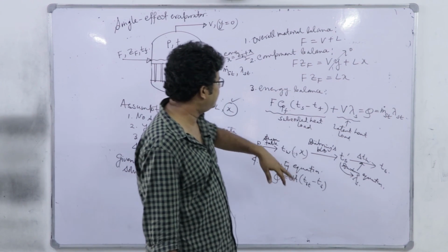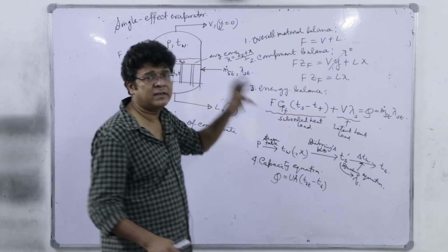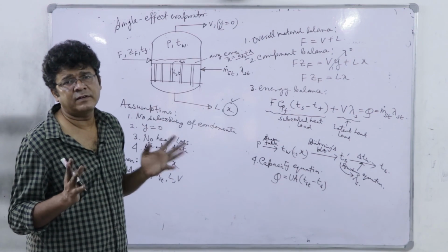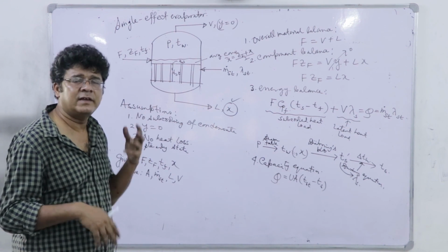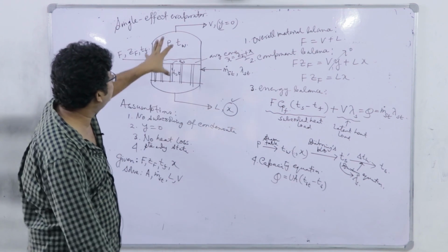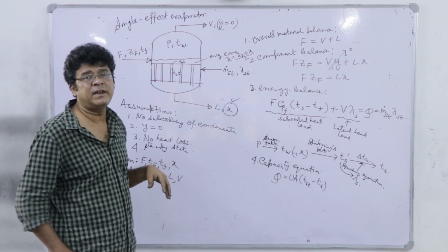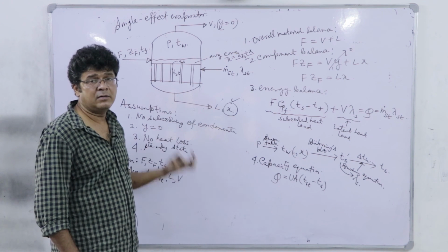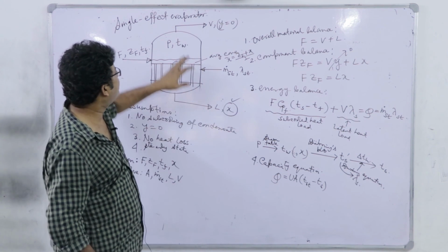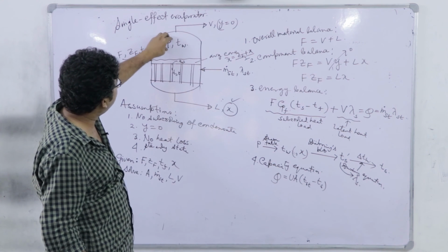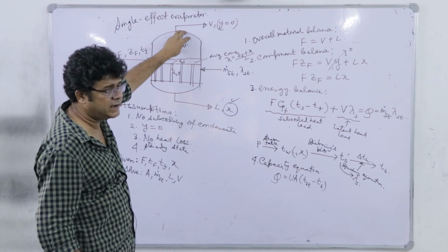We know X, and we have to fix certain pressure. Generally for single effect we can use this atmospheric pressure, but if it is heat sensitive then we may go for vacuum. That depends on the specific type of feed and my operating cost, allowed operating cost, right. So from there we can fix the pressure. Once we fix pressure we will get TW.